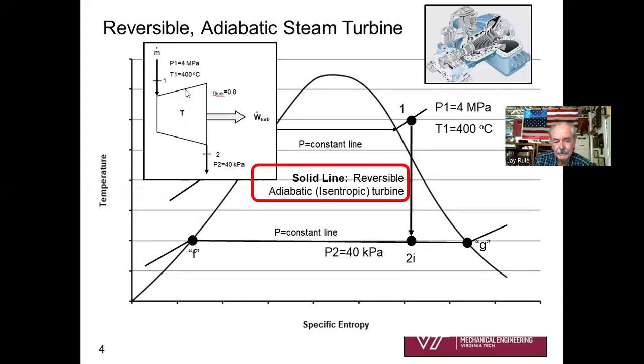Interesting here how typically we don't show a Q dot in. And that's because for most of our real world practical applications, nearly all of them, our turbine is considered to be fully insulated. So I haven't even shown Q dot in equals 0 on my sketch, but I am showing W dot out on my sketch. And I'm showing what's coming out here. Only the pressure is given, 40 kPa. So this could be a typical homework problem.